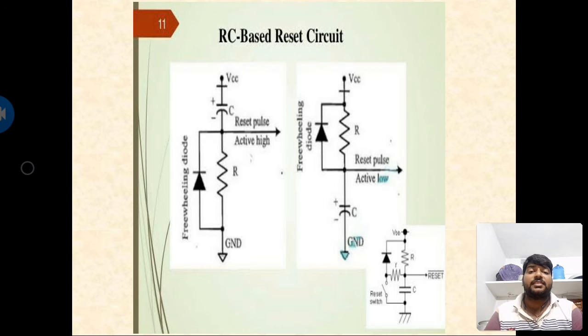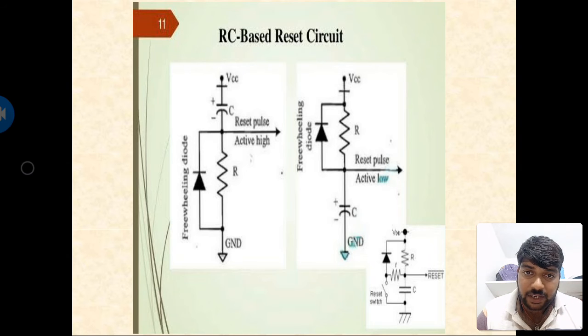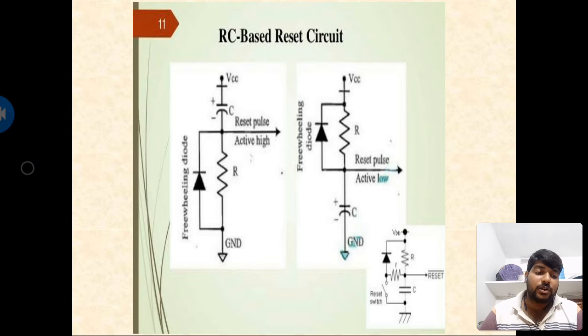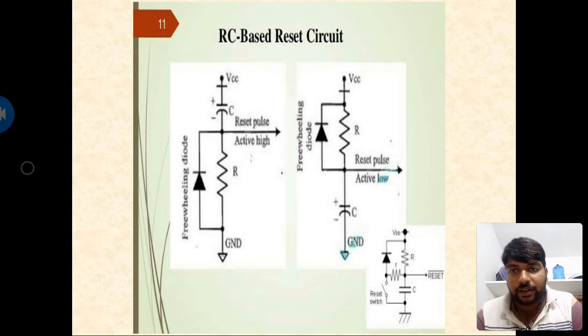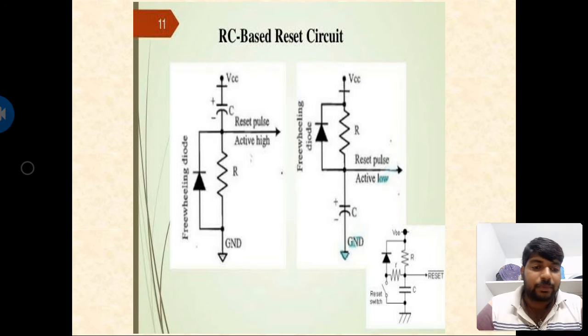that is a vector address at 0x00. That is the starting address of the interrupt vector table, at 0x00, when the internal registers and the different hardware systems of the processor or controller are at a prescribed state. The reset signal has two states, active low and active high, based on your reset circuit.